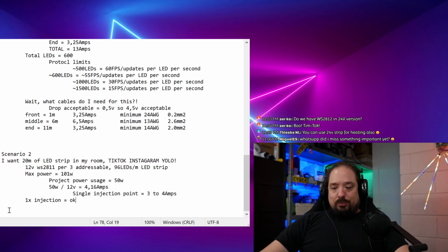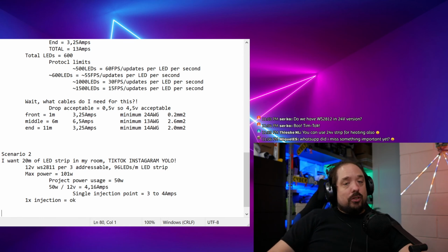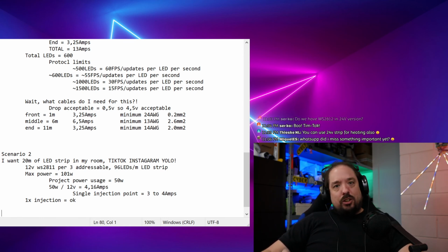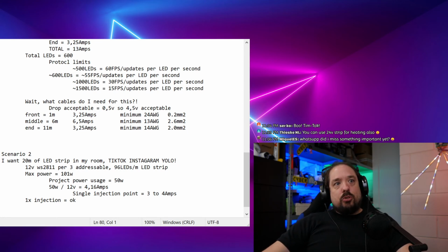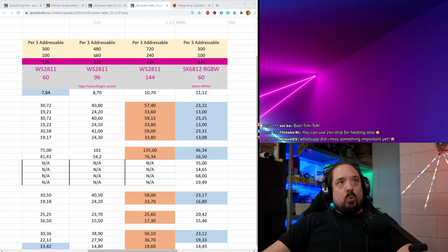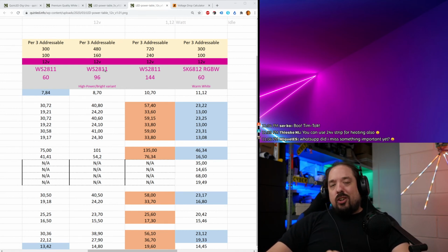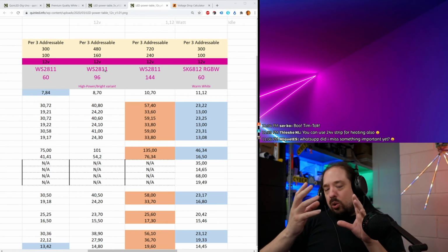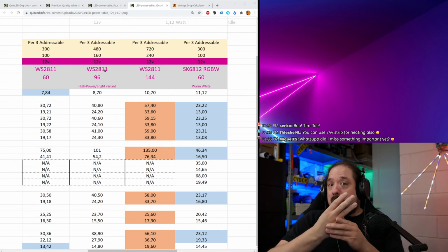But yeah. So now we have already 450 LEDs in total instead of 150 with 5 volt strip. And even better, the addressable zones we have is 160, while with the 5 volt strip we have 150 because we only have 30 LEDs per meter. But here we have 96 LEDs per meter. So although the addressable zones are almost the same, 150 versus 160, we have 3 times the amount of LEDs.